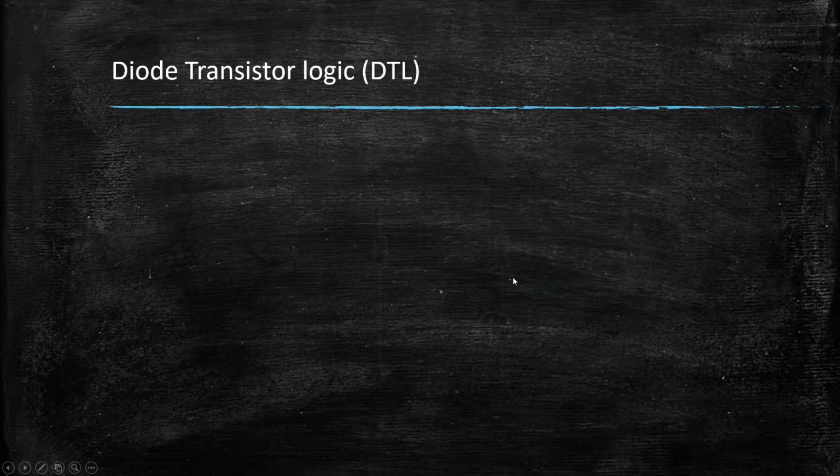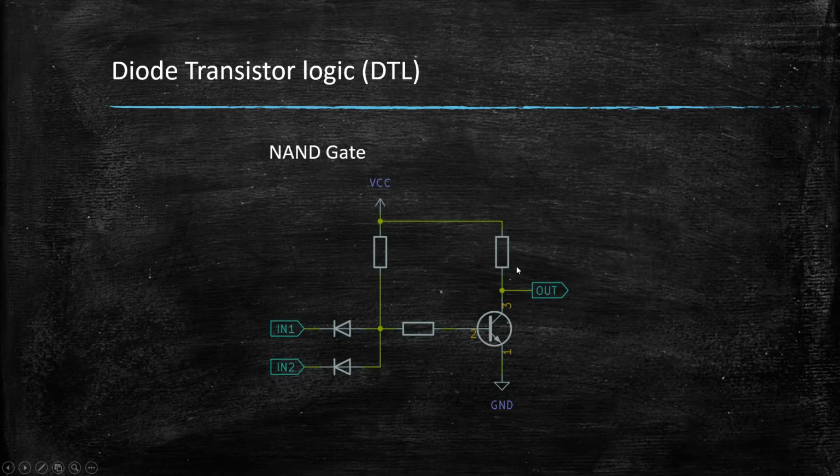transistors. So this is our first diode-transistor logic gate. Yeah, a very simple NAND gate. And as you see, the only thing it does is combine our input with a diode network here, which we just learned will only let current flow through the output transistor of the previous stage to ground.